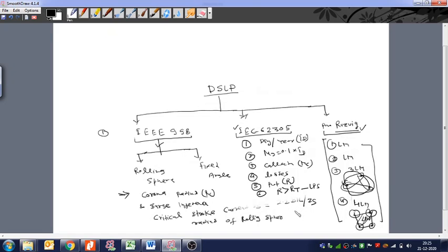And when it is required, then there are again 4 classes we have, and based on the classes we have the protection, rolling sphere radius and the mesh size. So if it is required, thereafter we select what LPS class we want to take. There are 4 classes, 1, 2, 3 and 4. Every class has a different mesh size and rolling sphere radius.